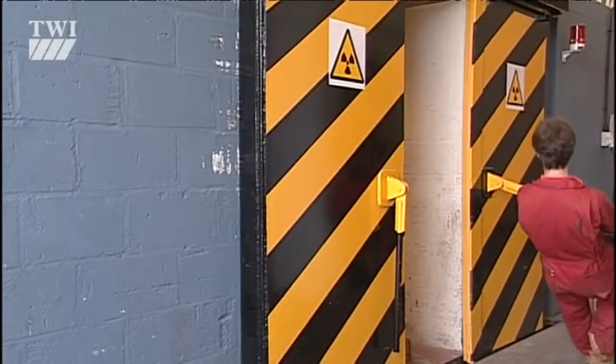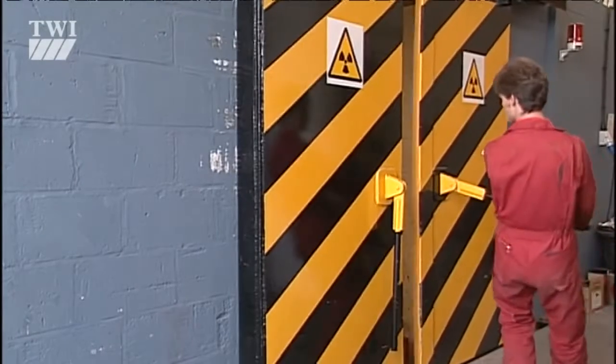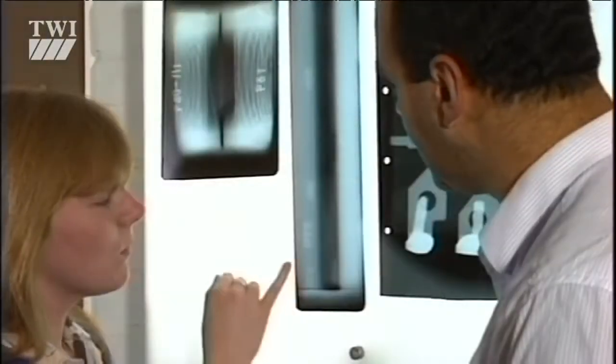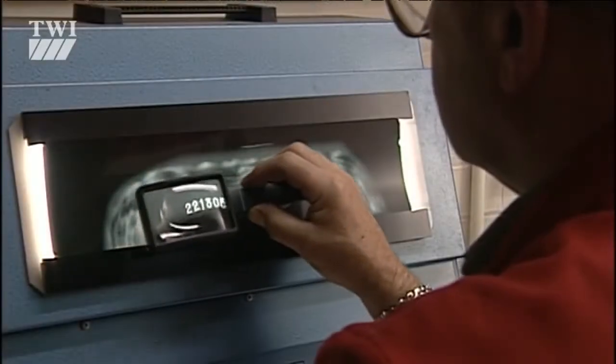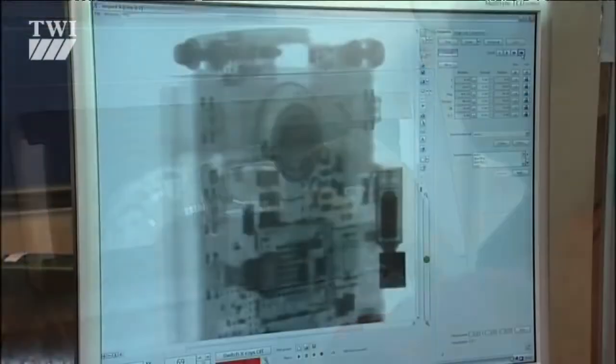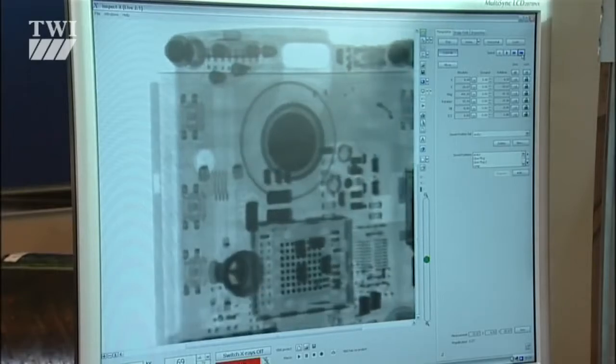Any volumetric flaws or discontinuities in the component allow more of the radiation onto the film, and this creates a darker image on the radiograph. In recent years, wet radiography, which uses photographic films and traditional darkroom technology, has been overtaken by digital radiography.